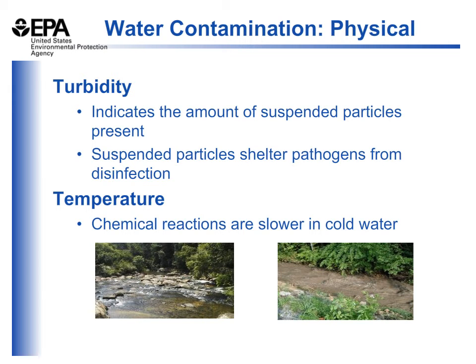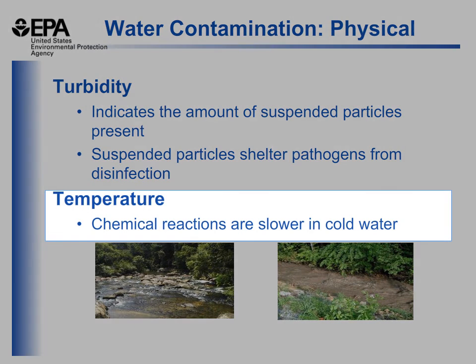The temperature of the water will affect the chemical processes that take place, especially for surface water systems, where we're looking to coagulate the suspended particles and flocculate them into larger clumps, which can then fall out of the water column through a sedimentation process. The colder the water, the slower this process is to take place.